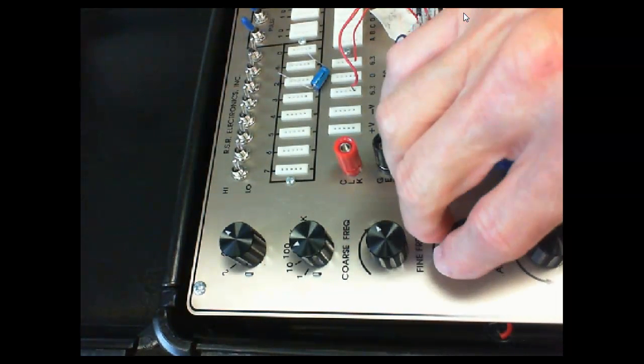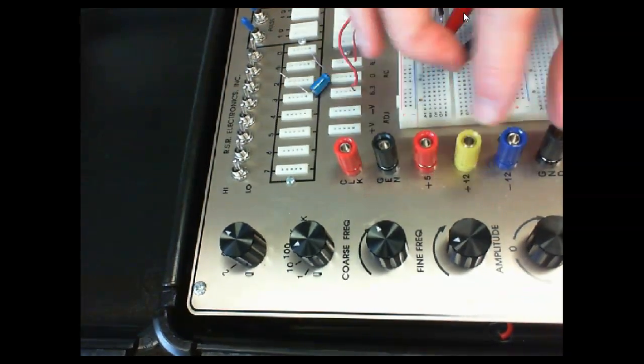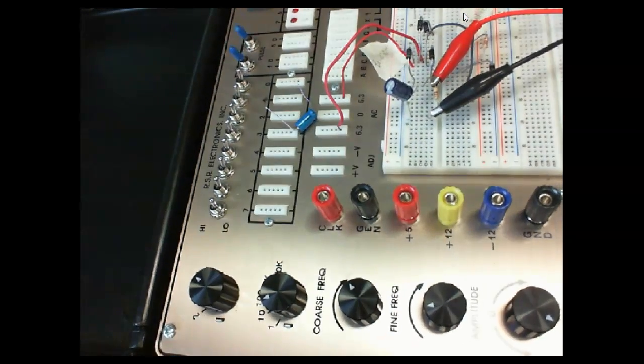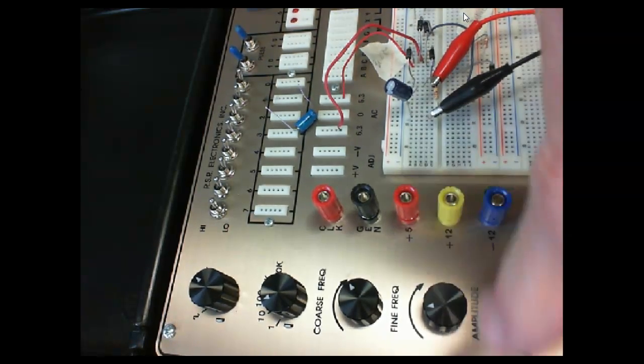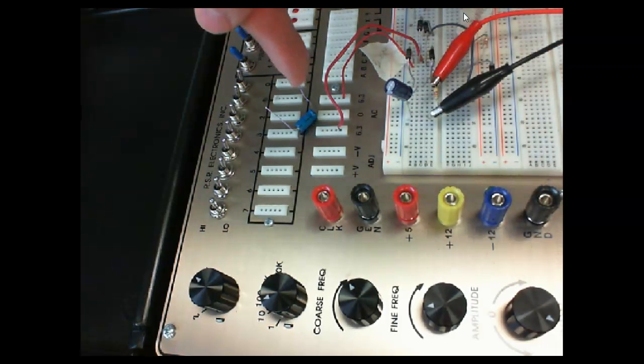And this is where you would fine adjust the frequency. This right here is plus 5 volts relative to this common terminal. So this is a big problem I have with this trainer. They label this guy here as ground, but if you measure between this terminal and the little small round one on your power supply, on your power cord, it is not grounded. So this is ungrounded.